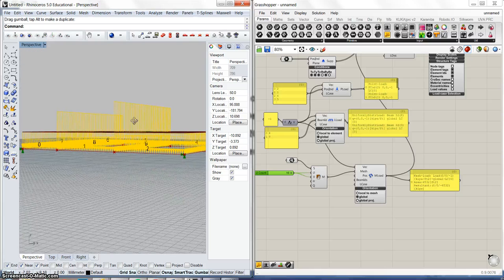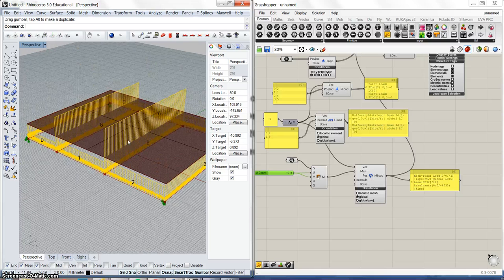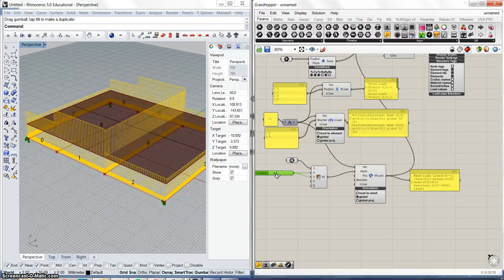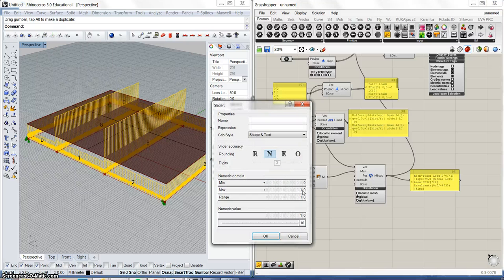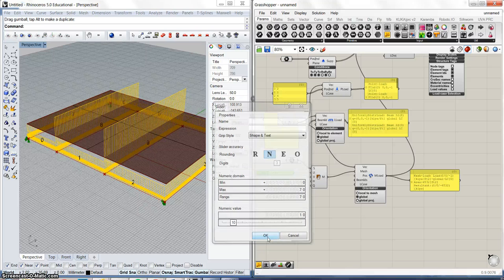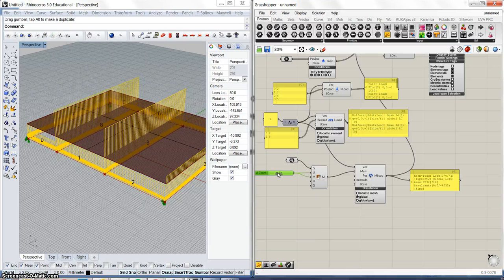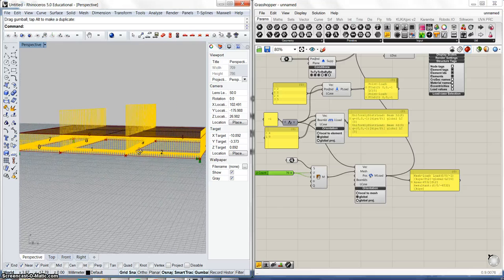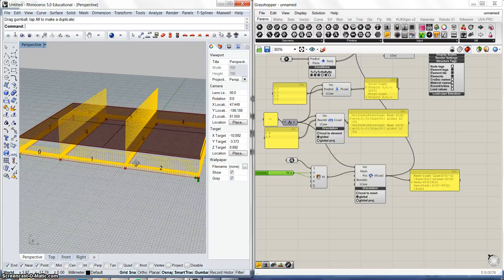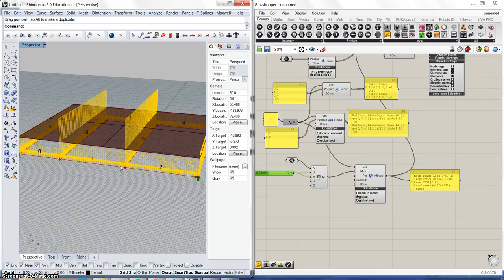So if you're using a mesh load and it's just not falling on all of your beams and something seems funny, it's good to bring your count up, and it might actually even need to be higher than 10 to get accurate enough data. You'll notice how this is changing as this is going through. So the greater your mesh is divided, the more accurate your data will be. So that's a good thing to know.